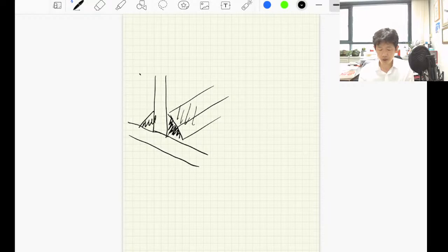The welding material. And then here I have some shear stress development, isn't it? The resistance provided by this welding is, for example, some kind of allowable shear strength. And then we need to consider the welding thickness.